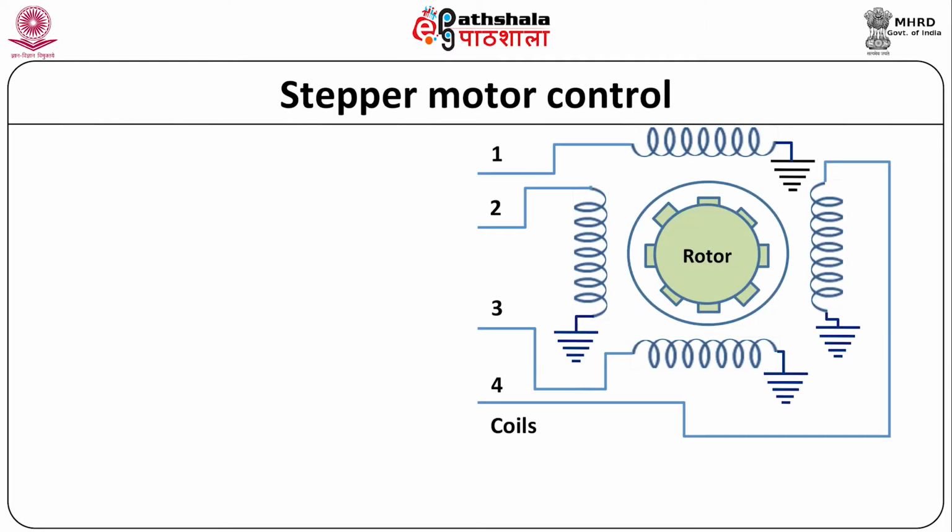Let us consider the architecture of a stepper motor. The stepper motor does not work on constant supply. It can only be worked on controlled and ordered power pulses. There are two types of stepper motors, unipolar and bipolar stepper motors. As shown in the figure, in a unipolar stepper motor, there are 4 coils. These coils are driven by pulses and the other ends of the coils are grounded. A shaft is attached to the rotor, whose rotational angle needs to be controlled by the digital control circuit.